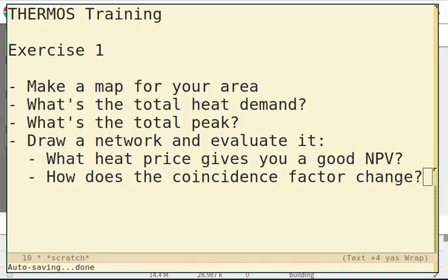If you've enjoyed this video, why not try using some of what you've learned to answer some questions for a place that you're connected to? You could make a map for your area, and you could use that map to answer a few questions about the area. You could find out the total annual heat demand. You could find out the total peak heat demand. You could draw a network and evaluate it, or draw a few different networks and evaluate them and see how they compare. You could change the heat price to see how that affects the NPV of the solution that gets produced. You could look on the map at the coincidence factor for pipe work in the network and see how it changes according to how far up or down the network the pipe is.